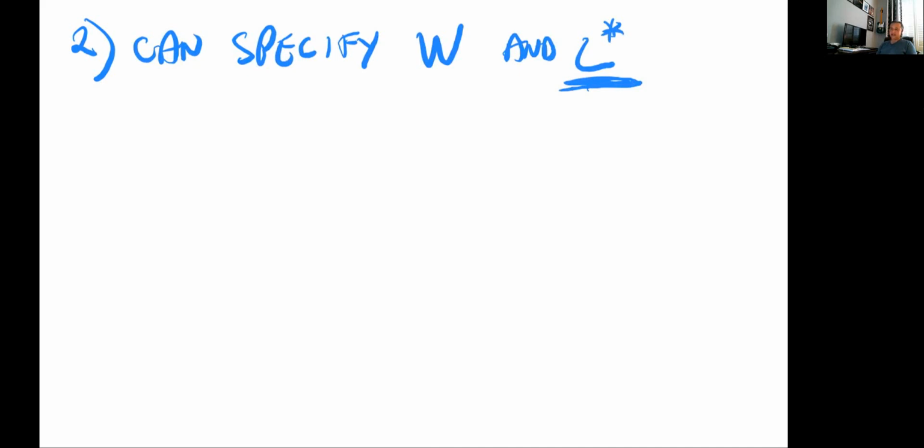So unless it's really necessary, I don't want to make the transistor geometrically fatter than it needs to be. I can make it as long as I want geometrically, but I want to keep that critical dimension, because when they do the process control, this is a fabrication or manufacturing process control, they're going to target a number here, okay?